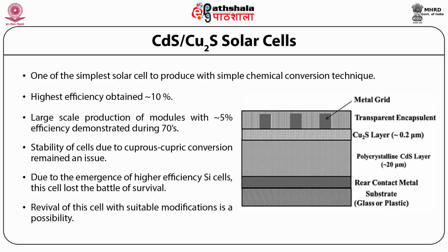from polycrystalline material. There are several advantages of the cadmium sulfide copper sulfide solar cell, such as easy fabrication, can be mass produced, large area cells can be made in rectangular shape, reducing the spatial losses, and energy consumption in the cell production is low.